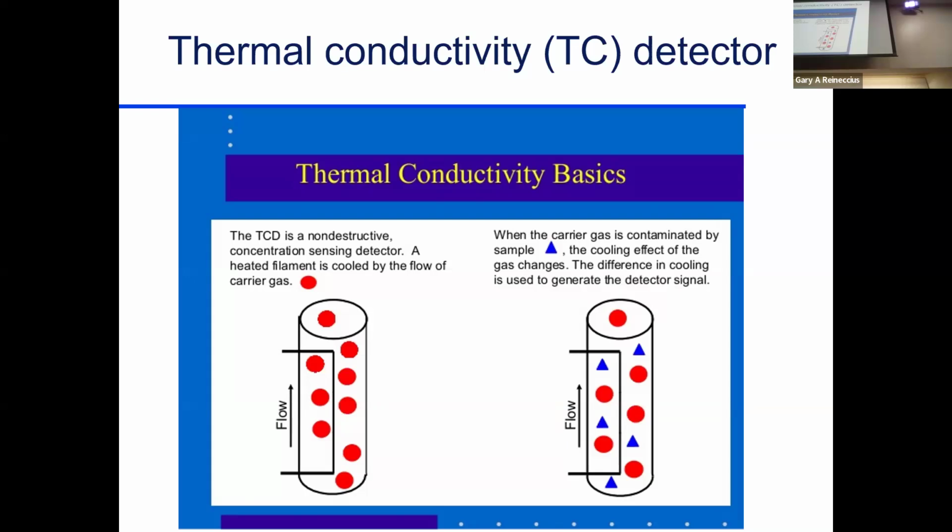Oh, thank you. Okay, that's our analytes coming out. The orange, the red parts. Okay, so they're making these molecules big and round. But anyway, that's what's coming in here, and the effluent from your column, all that carrier gas, mobile phase, and your analytes are pushed through this and out. So they're coming here. This is just an electrical filament. And what the machine is doing is monitoring the temperature of this.